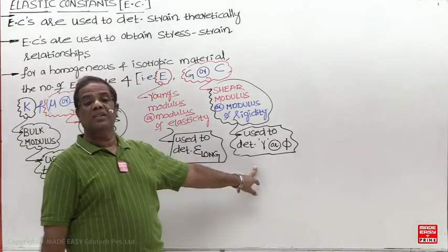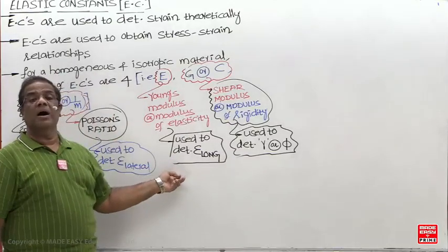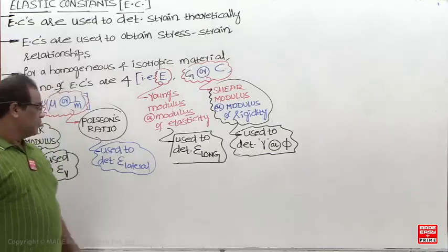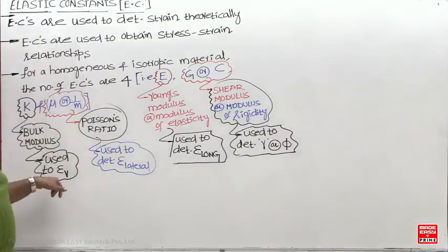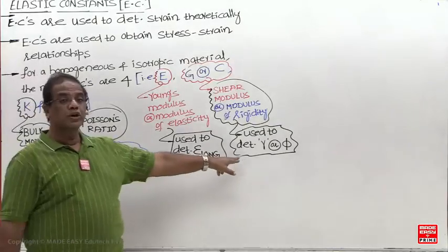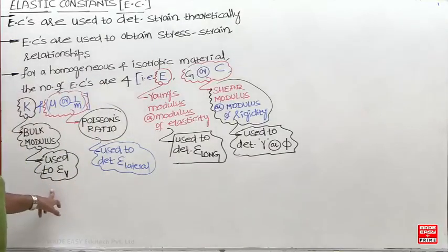Pure shear is sigma x, sigma y 0, tau xy equal to tau. Uniaxial means sigma x equal to sigma, sigma y and tau xy 0. And this is the hydrostatic state of stress, that is sigma x, sigma y, sigma z are equal and like in nature. Just now you studied it. Hydrostatic is triaxial. E and mu are under uniaxial. Pure shear means biaxial state of stress, but this is triaxial. There are many triaxial states, but the specialty of this one is that sigma x, sigma y, sigma z are equal and like in nature, and tau xy, tau xz, tau yz are 0.